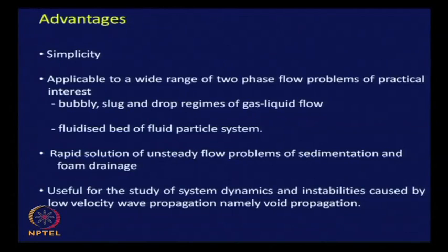So, you will find that for most of the cases, particularly for the intermittent flow pattern which we had defined in our flow pattern chapter, as well as a few of those dispersed patterns which we had discussed, the drift flux model is going to be extremely advantageous. Okay. So, firstly simplicity, secondly it is applicable to a wide range of two-phase flow problems which are practically encountered in industries.